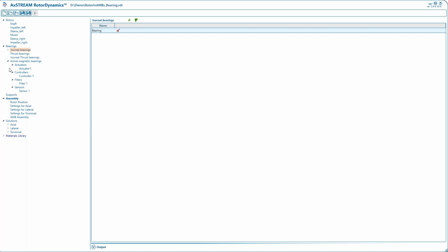Perfect. The next question I have here: Softinway has a standalone module for bearing calculations. Why are active magnetic bearings simulated in the module for rotor dynamics calculations? Thank you. The rule of thumb for fluid film and rolling element bearings is to calculate reactions in bearings by static gravity analysis, then apply them during bearing calculations, define the stiffness and damping characteristics, either frequency dependent or not, and specify them during rotor dynamics calculations.